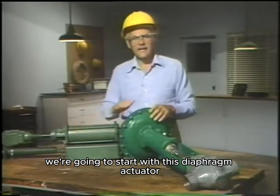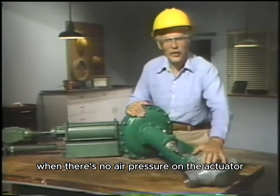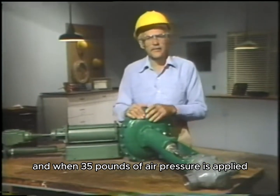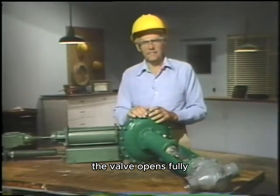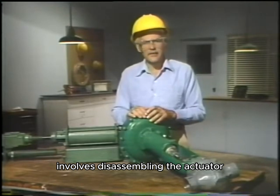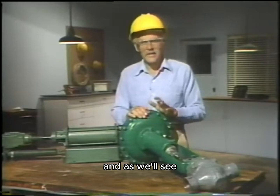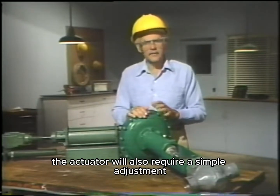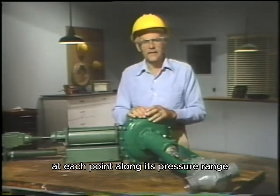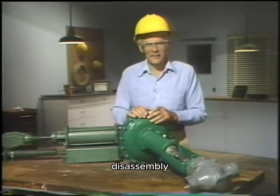We're going to start with this diaphragm actuator. It's a single-acting type that operates a valve. When there's no air pressure on the actuator, the valve is closed. And when 35 pounds of air pressure is applied, the valve opens fully. The routine maintenance procedure we're about to see involves disassembling the actuator, inspecting its parts, and replacing the diaphragm. And as we'll see, the actuator will also require a simple adjustment, so it'll position the valve correctly at each point along its pressure range. Let's start then by going to the shop for the first part of the maintenance procedure, disassembly.